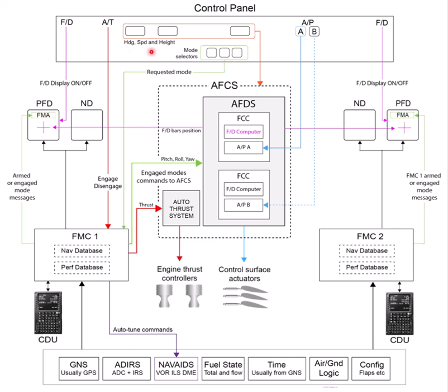It will pitch down if the speed becomes too slow, and it will pitch up if the speed becomes too fast. So that's the beauty of flight level change. It will control the speed on the autopilot, so if my thrust varies a little with altitude or with engine performance, I'm safe.